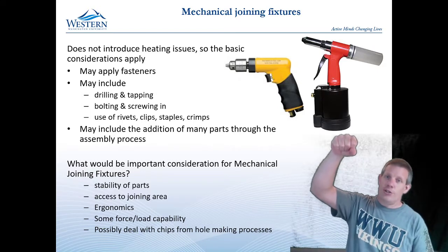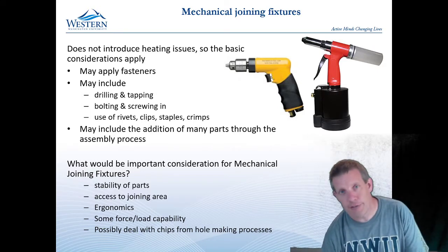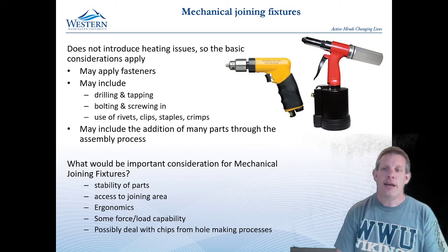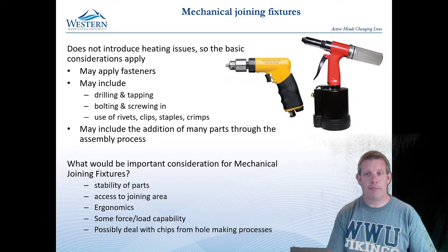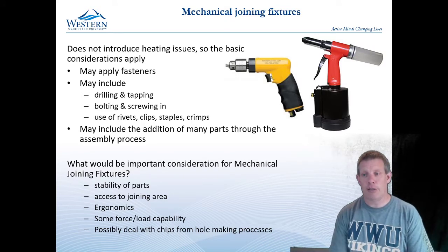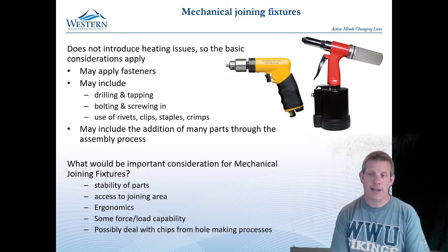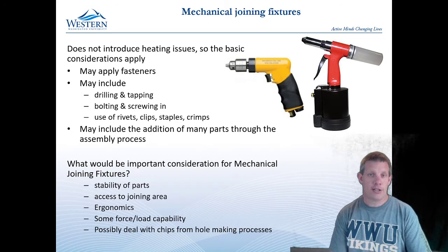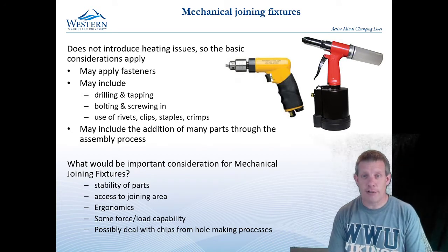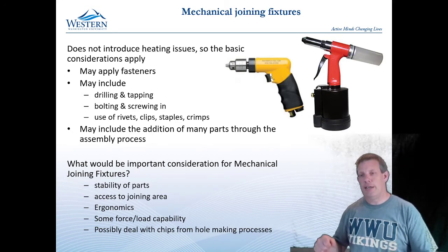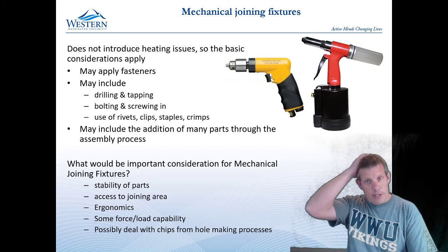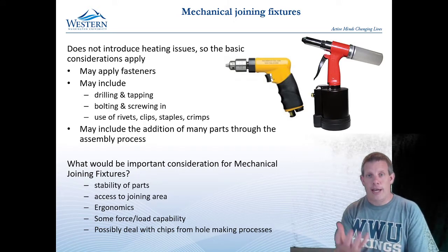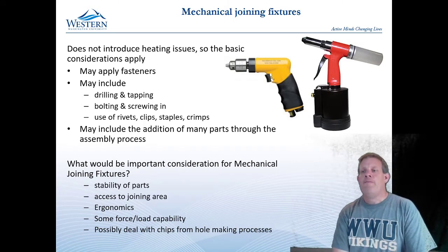Yeah, if I'm having to drill way up above my head, then I'm having to drill way down by my feet. That's certainly going to affect the person. And so a better fixture might be laid out horizontally. But one of the things that you'll find is that often when you put things out horizontally, first they take up a tremendous amount of room. But secondly, you can also get to the point where they're much harder to unload when they're horizontal, and harder to support because you don't have gravity helping you.